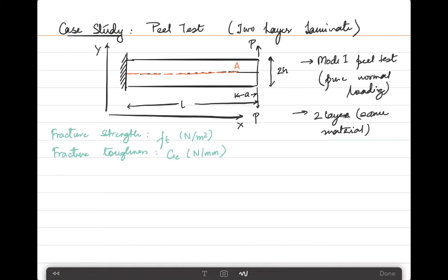When the crack tip appears over here, if the mesh is not sufficiently fine, then local softening will occur, causing a sudden release in energy or a snapback behavior, and we will get a failure of convergence. So the mesh therefore has to be sufficiently fine, causing large computational effort to be spent in solving this problem.